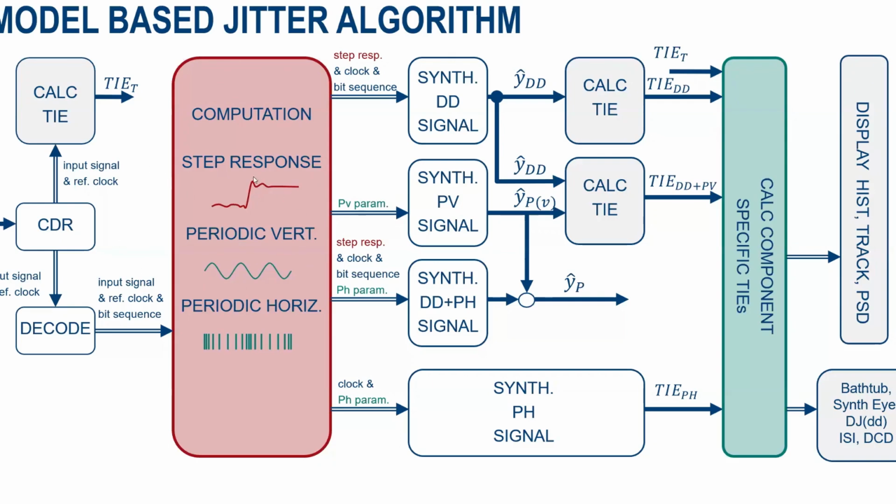And that step response that comes out contains all of the channel related effects. And so in a way, it's a way of measuring the frequency response of the channel without accessing both sides of the channel, essentially just by looking at the waveform.